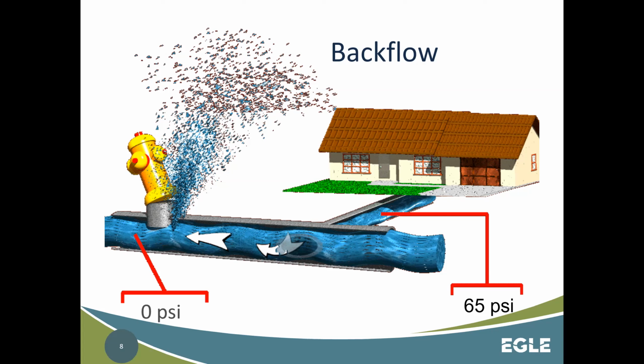So with that backflow event occurring here, the water's going to run out of the house, and then it's going to come out here. We know that this is not supposed to happen. When you hit a hydrant, it's supposed to blow out water. This is a Hollywood picture, just so we're all aware, because this would break away the shackle and close the bottom valve so that it wouldn't gush water. But anyway, this is a backflow event as back siphonage.